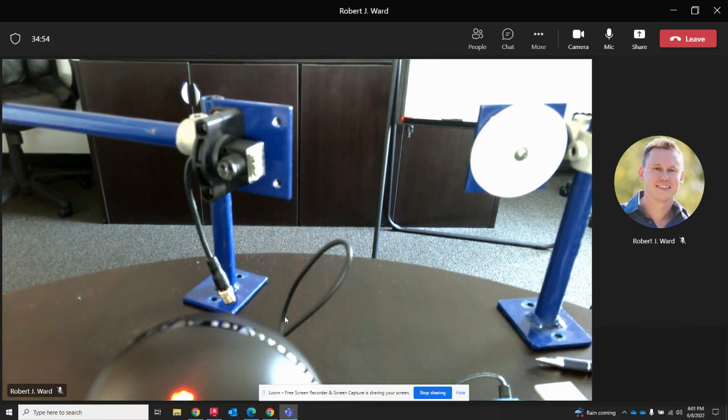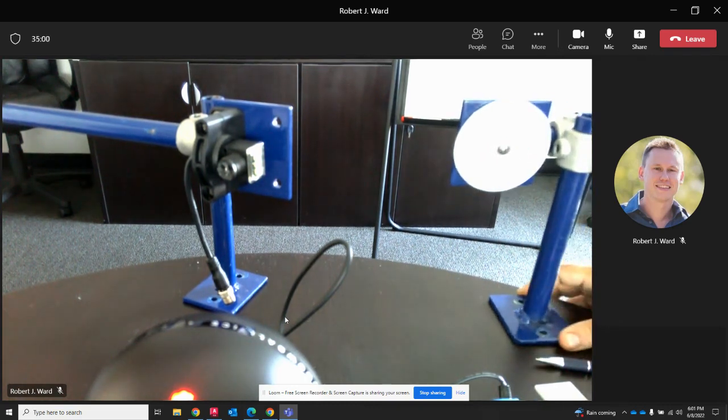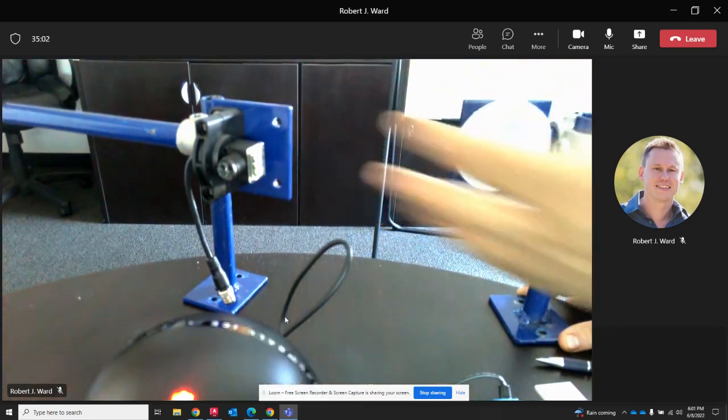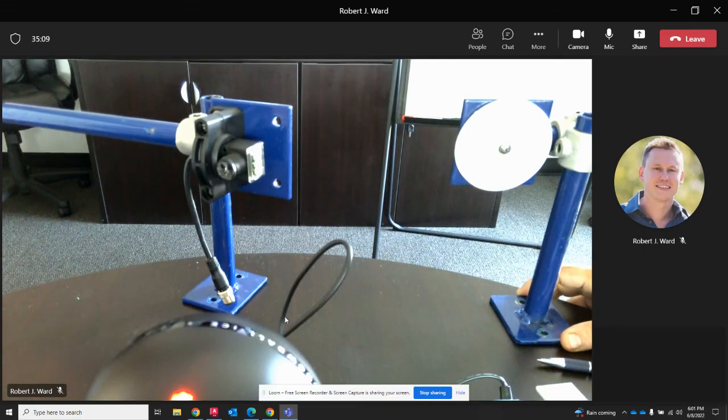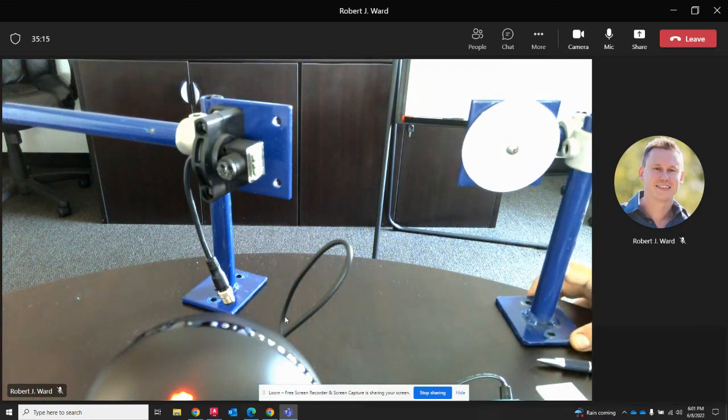And the other big reason we switched to these brackets is because you can mount the base of the bracket in a location and have the reflector sticking out over, say, a motor or a gearbox, say at the end of a sorter, right? We want a photo eye in a specific position. This allows us to get the photo eye and the reflector in that position while offsetting the mounting base itself.